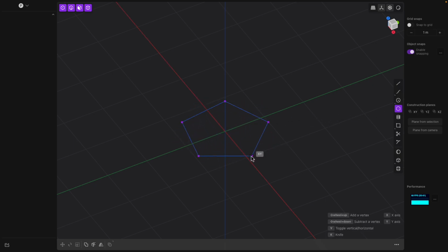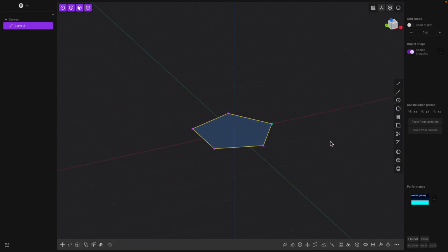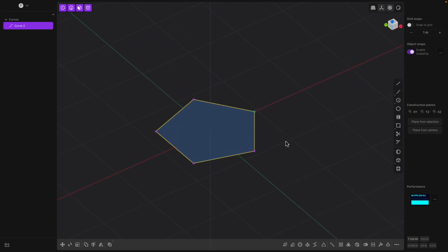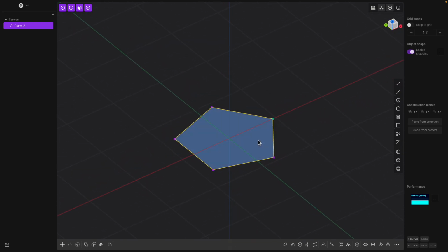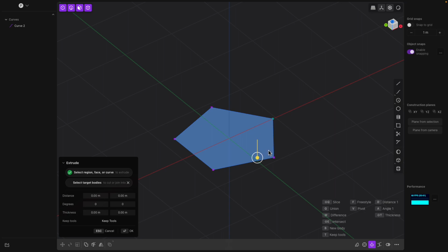When we draw it, it's like an n-gon, right? And then you can hold shift and wheel up and down, and you can get a hexagon. Let's try this for now. Five-sided objects, and then let's try extruding this area like normal.